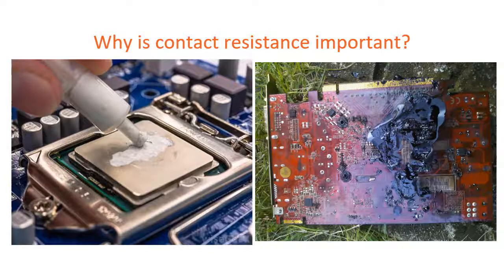The CPU often generates a lot more heat than can be transferred away from it without the use of a heat sink. The contact resistance between the underside of the heatsink and the CPU is significant. Neglecting it can have serious consequences on the lifetime of a computer.